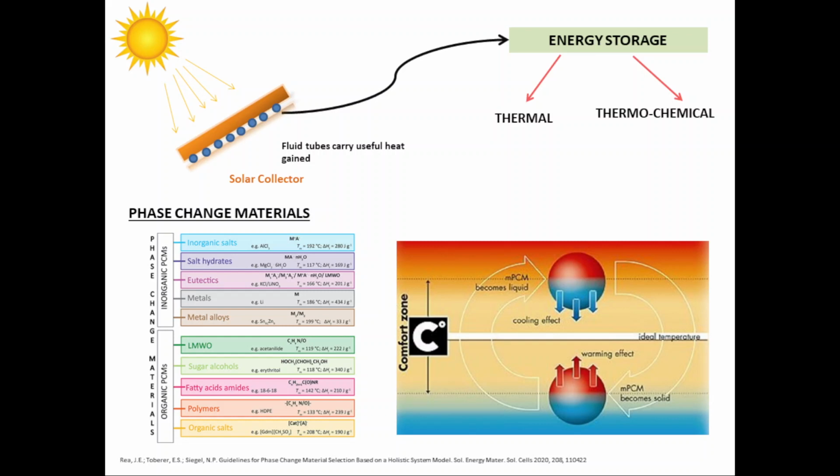For example, if you take water at 0 degrees Celsius and start heating that water until it becomes vapor at 100 degrees Celsius, the amount of heat gained by your water between 0 and 100 degrees Celsius is called your sensible heat. But at 100 degrees Celsius, the water undergoes a transition. It starts moving from its liquid phase to the vapor phase. This phase transition is called your latent heat energy storage. This can be specifically harnessed for our thermal energy storage system.